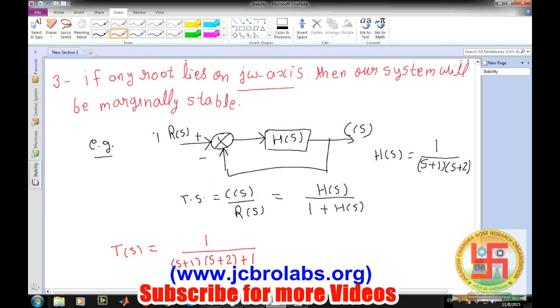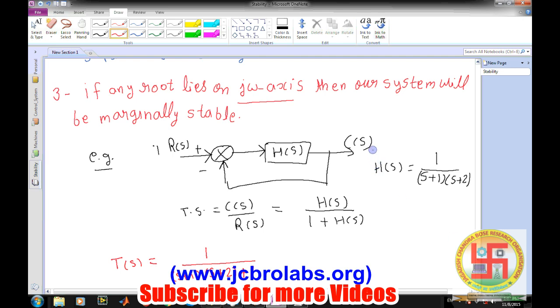If we talk about an open loop system, meaning when we have only this transfer function, this is the open loop transfer function. This transfer function is stable, because it has both the roots on the left side of the S plane, minus 1 and minus 2.